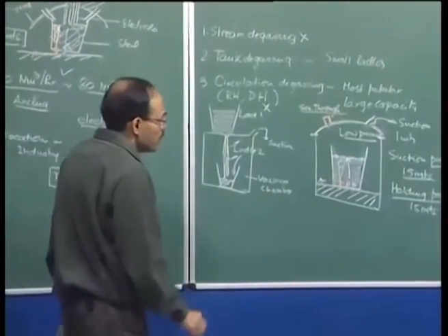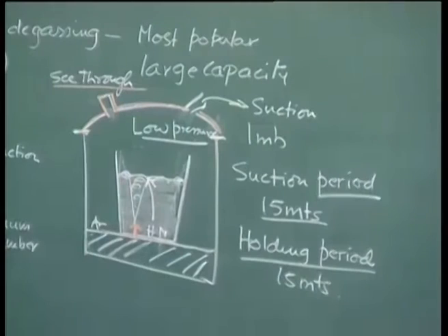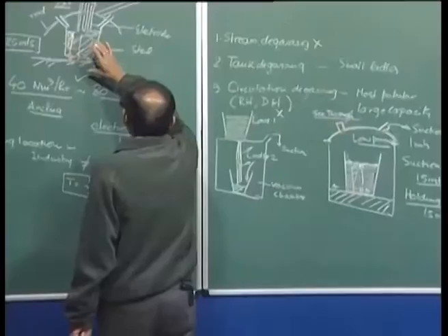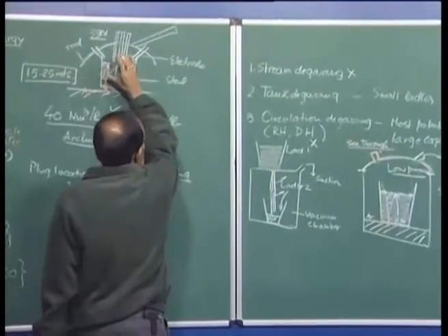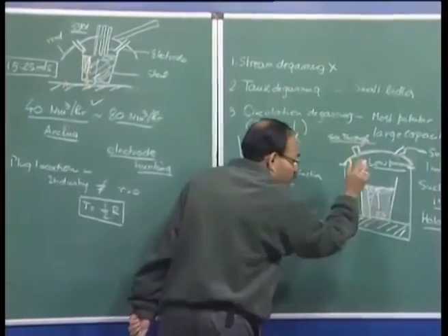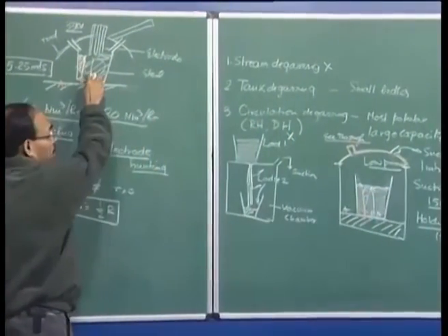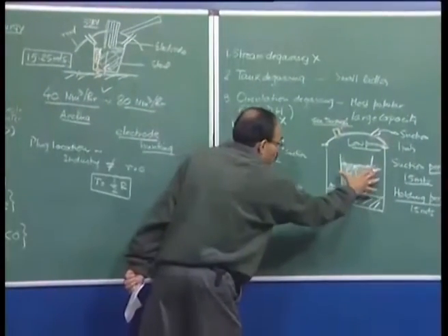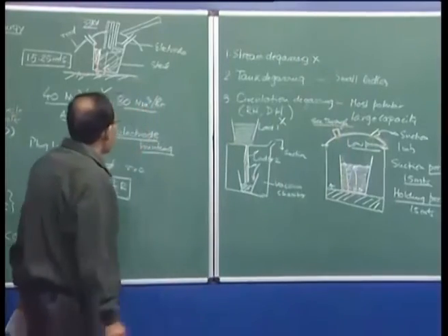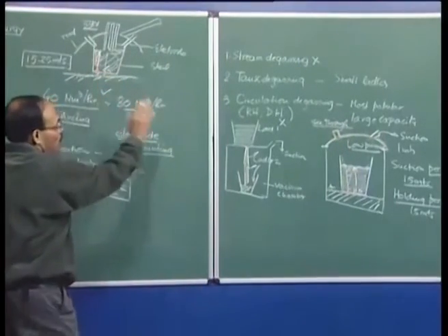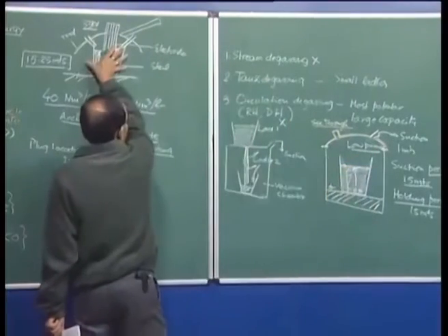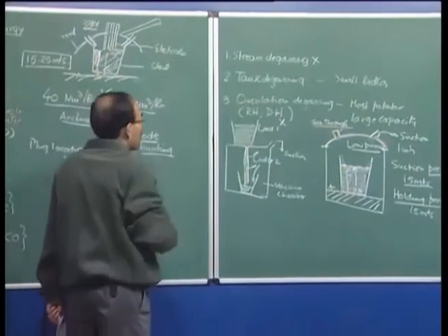Now, in the degassing process, there could be a significant drop in temperature also. Therefore, the material that is brought here is actually overheated to some extent in order to compensate for the degassing process, because LF is before the degassing process. To compensate for the temperature which is going to be lost during degassing, we are going to notice a temperature drop, and this temperature drop has to be compensated by the ladle metal, by the LF station.